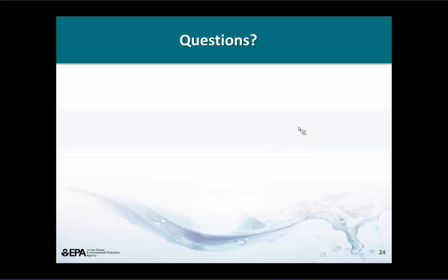Okay, Michelle, right now we only have 2 questions. The first one is, what is the smallest area that you can accurately model with SWMM? We can model something like 0.1 acre. In terms of sub-catchment, we can model 0.1 acres, at least we do with the stormwater calculator. We can do hundreds of acres with SWMM. I don't know that we have a smallest area per se. I guess if you took a pail and tried to model it, you should be able to do it with SWMM. As far as I know, there's no limitation.